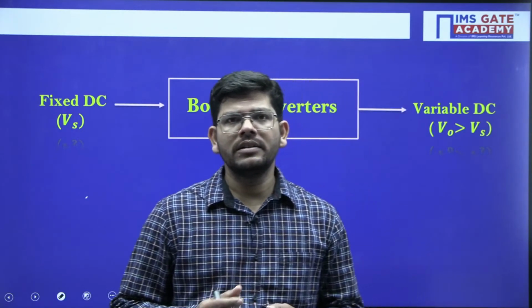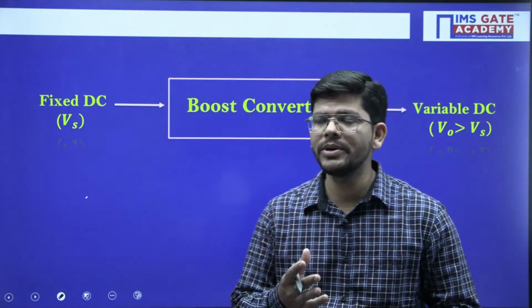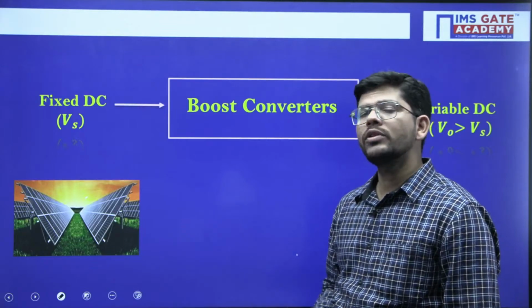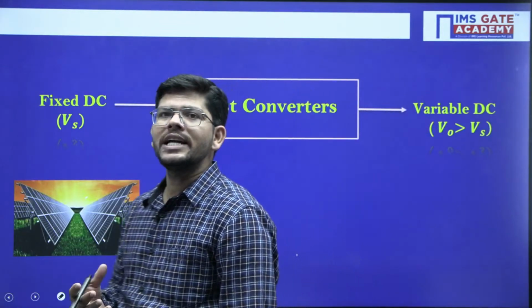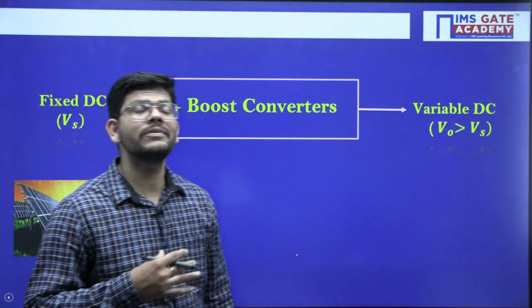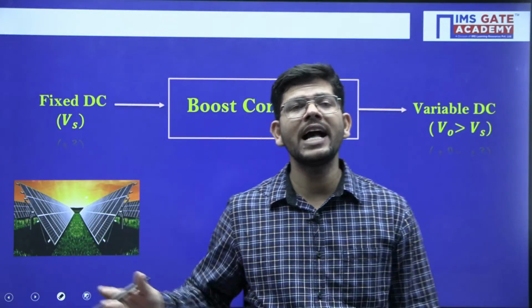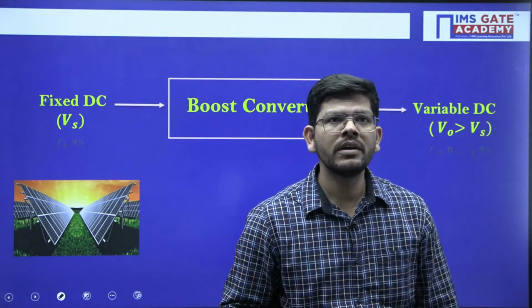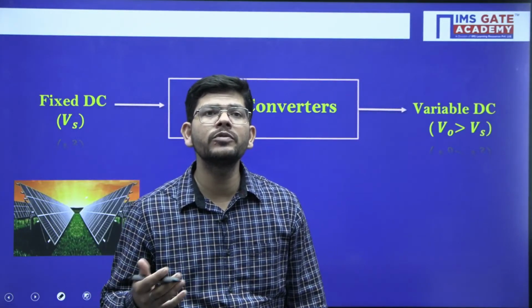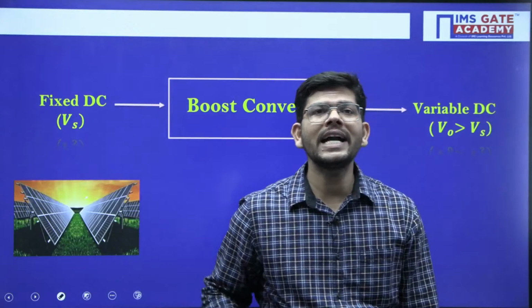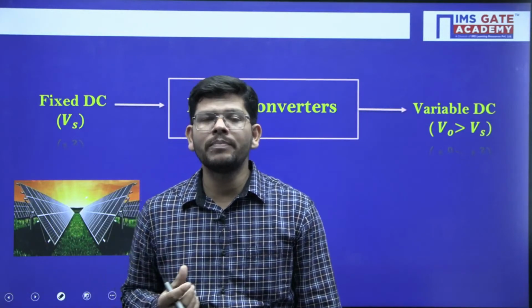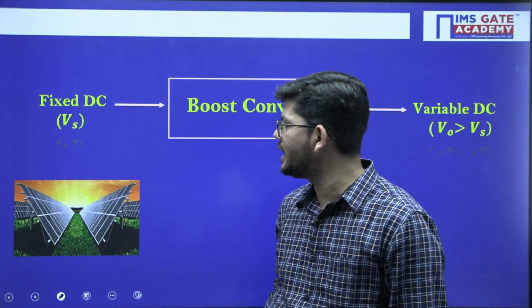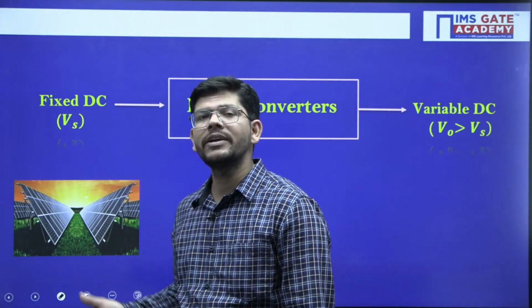Why is it desired to have the boost converter? Because of applications like solar. The voltage that we get from solar panels is very low, and suppose we have an application, for example charging a battery at home, and many other applications. If we need to supply to the grid, we need to increase the level of that input DC voltage, and that's why we need a converter.